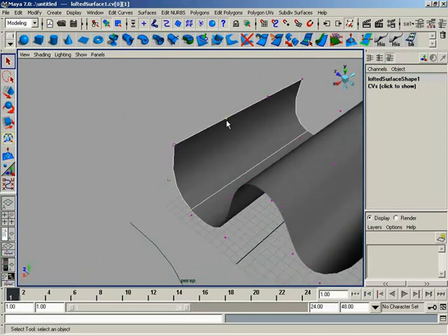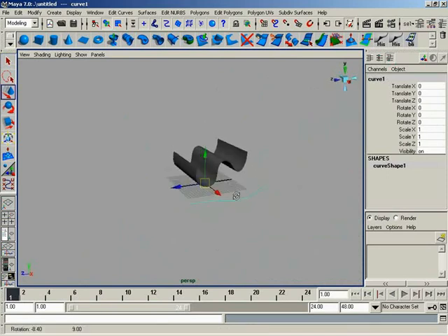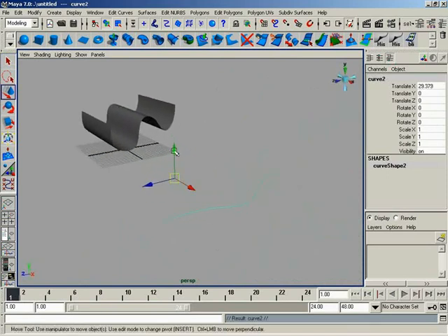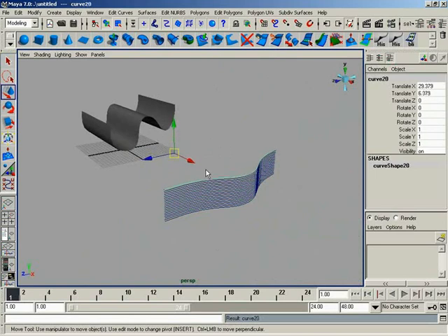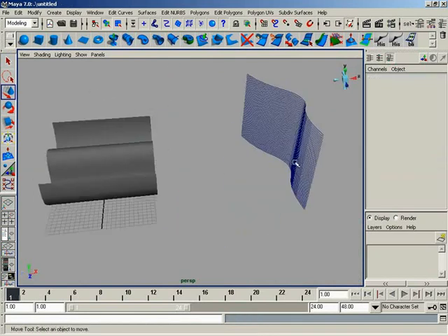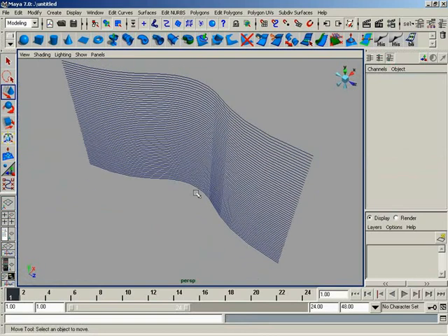So there's V right there. I highlighted it for you. And how does that work? That creates a surface by basically taking one curve, such as this curve, just as an example, and we make an infinite number of duplicates of it. In fact, watch this. If I take this curve and I Shift D it and make several duplicates of it, I'm just duplicating away like mad, hitting Shift D over and over. There we go. Now what we have is a series of curves that is simulating a NURBS surface.